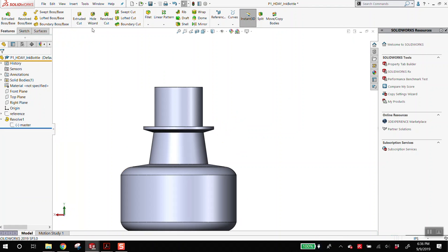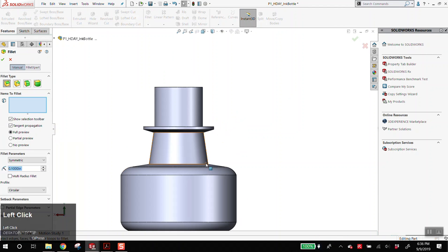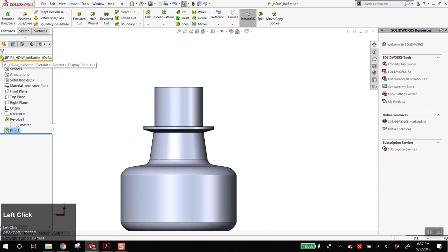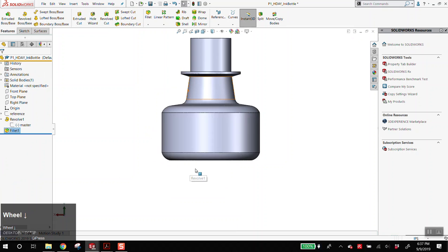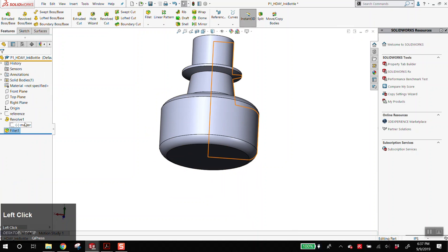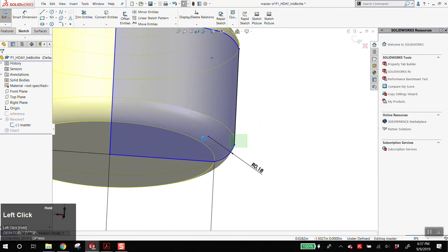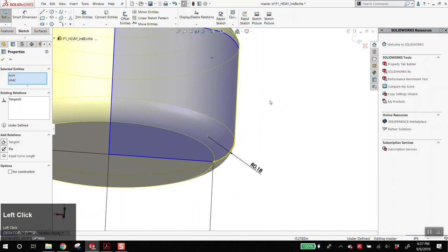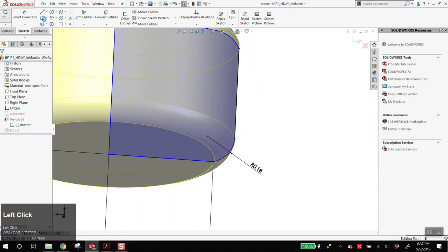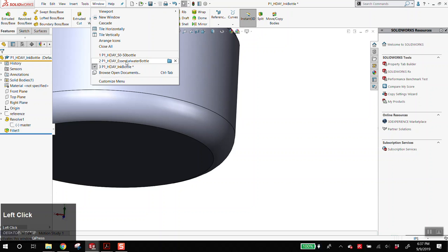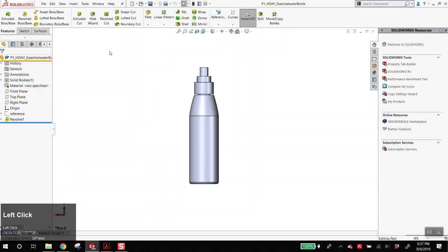So hopefully all this feedback made sense. I would say throw a fillet on here. Given the fact that you fixed this now, my feedback on these isn't necessarily pertinent anymore. It's all the same stuff. Make this tangent in here, like this. These two should be tangent to each other, or if not, throw a fillet on it. Okay. Are you good then? Do you have any other specific questions?